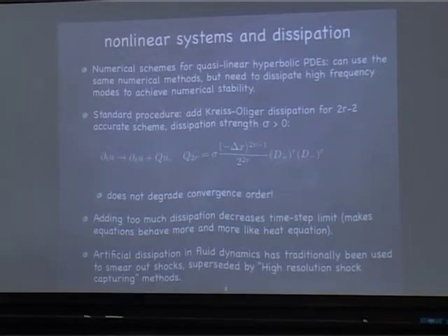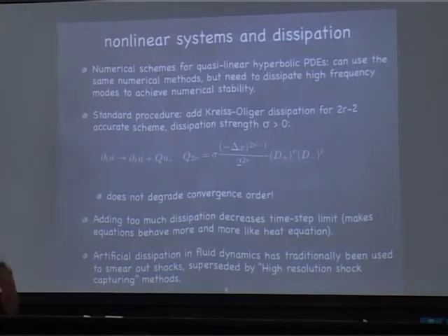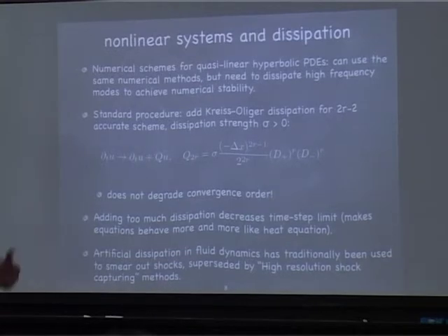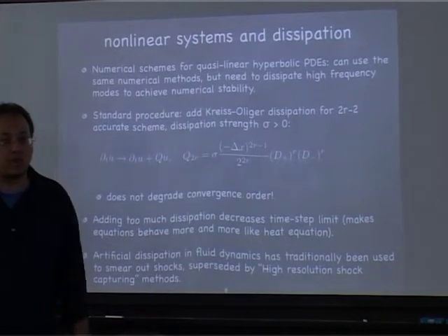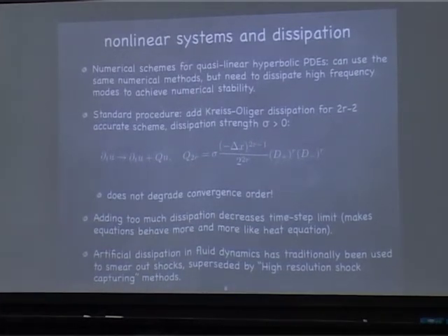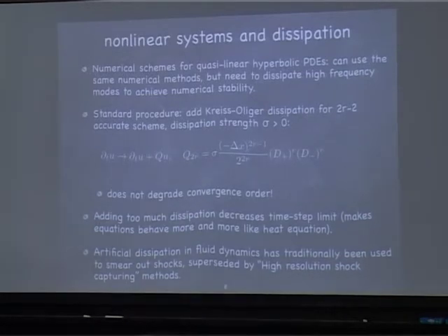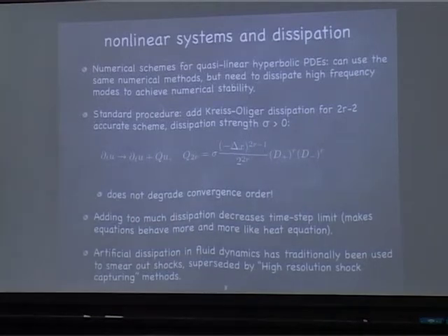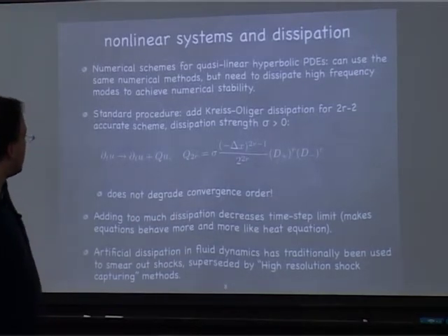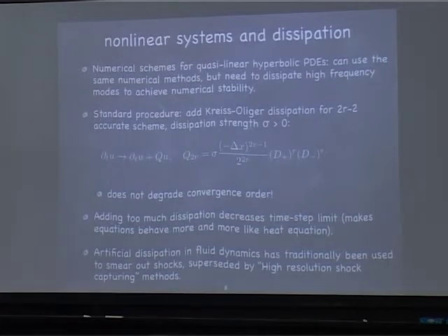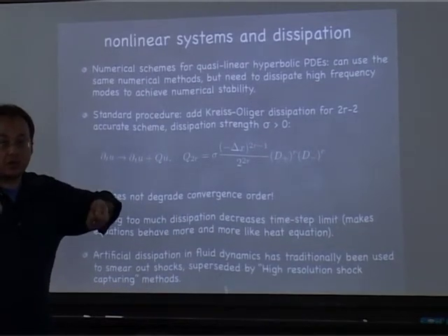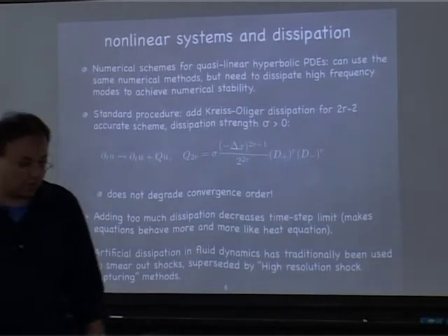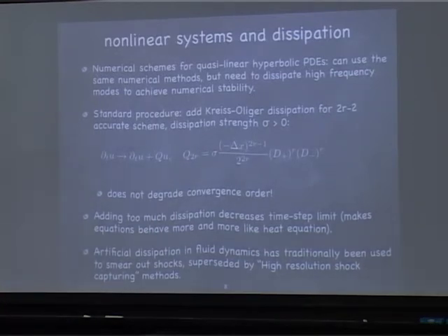So you cannot just damp as much as possible, because at some point you just hit the CFL limit, and you have to either make the time step smaller or you have to make this smaller. Okay, you cannot have a hyperbolic equation and make it look as much like a heat equation as you want, because it just behaves differently. Okay? So the usual thing is there's not a lot of risk to damp out too much, because if the amplitude becomes too large, it just behaves too much like a heat equation, and the time step becomes very small.